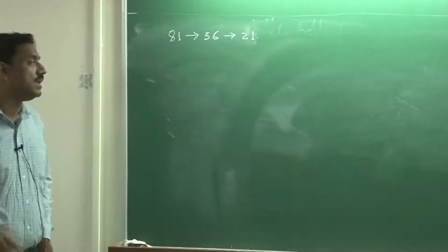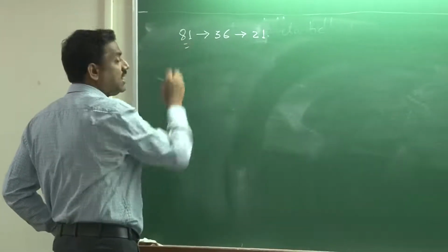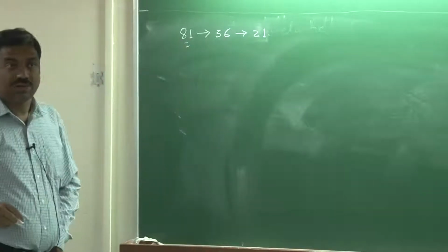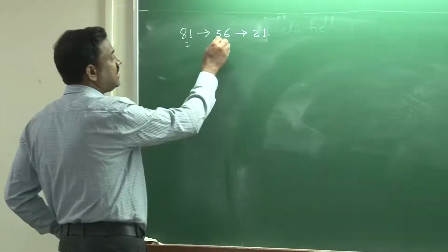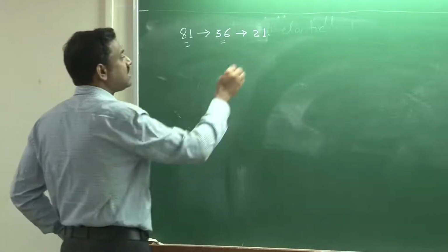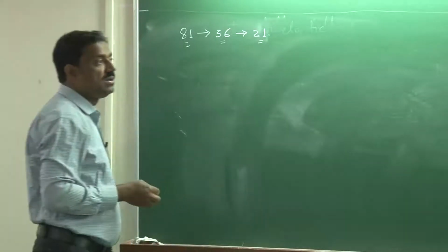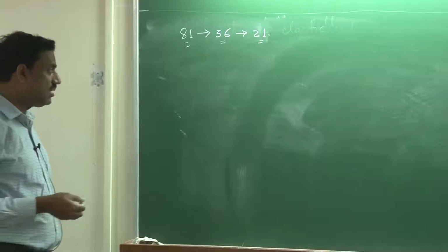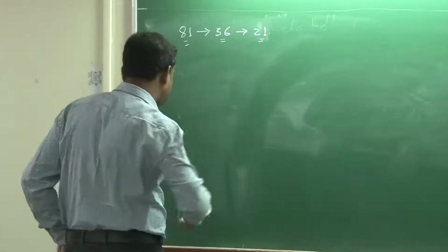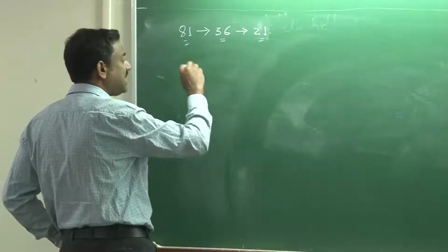Okay. So, first is the generalized component in a fourth order elasticity tensor, then we exploit the symmetry of representation of the stress tensor, then we exploit the reciprocal theorem or energy conjugacy. Now, we will see that this can be further reduced.